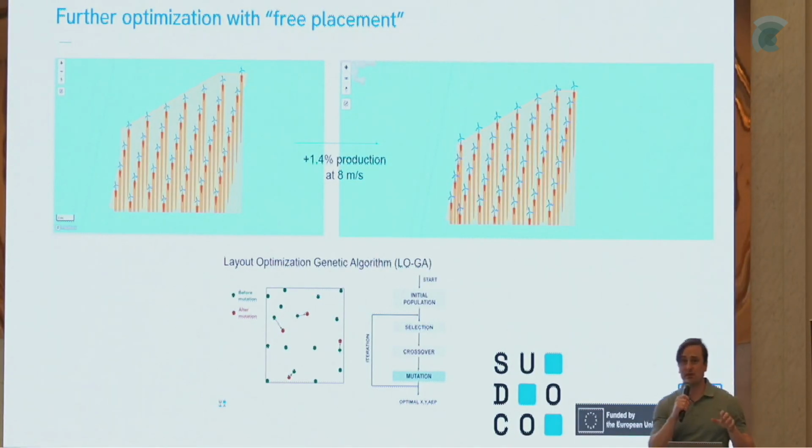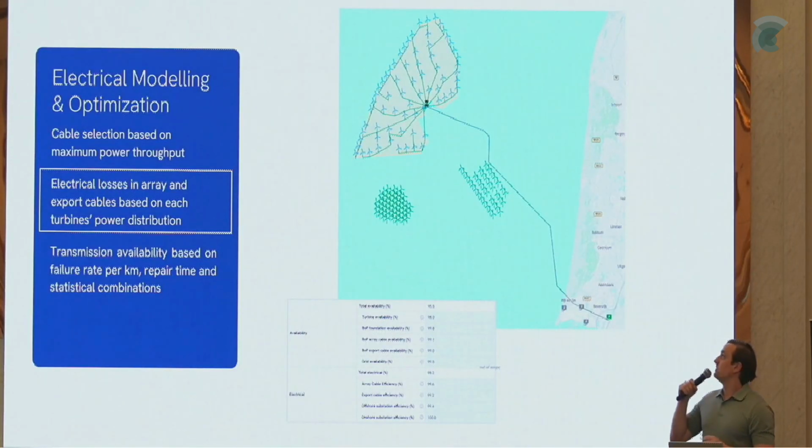This also works when you have a time series and you're using a map or farm where you're doing the horizontal extrapolation. From the measurement points into the exact grid point, you can also simulate what is the exact improvement. And we estimate here more or less between 1% and 3% improvement. From here, you go into the process of techno-economic assessment that includes the optimization of electrical design. We can't only optimize where the location is for the offshore substation, we also need to optimize the shortest distance when you're designing the arrays and which cross-section you should use.